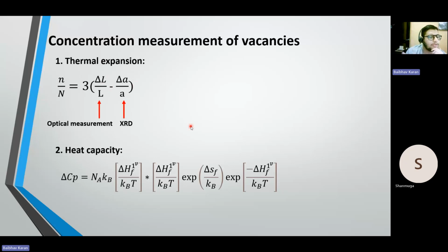They don't contribute much to the increase in length or the change in density. The density change occurs only due to the thermal expansion from the heat we are giving. Vacancies are not involved in the density change of the material. So density is a structure insensitive property. That was what was concluded from the problem.